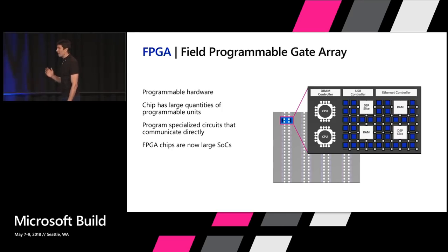FPGAs have programmability that's somewhat like the general purpose CPUs. They're massively parallel, and they're implemented as programmable hardware switches. So they look a little bit like programmable ASICs. And what that means is you can put algorithms on it and map them to this programmable hardware fabric and get close to ASIC type performance, and draw a lot less power than you would with the general purpose CPU.